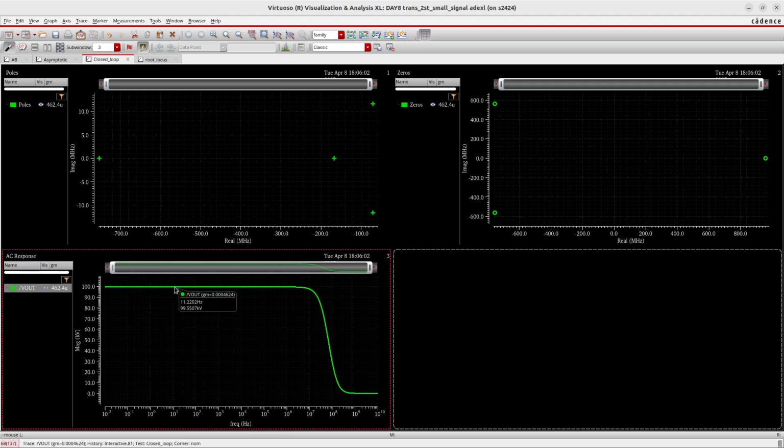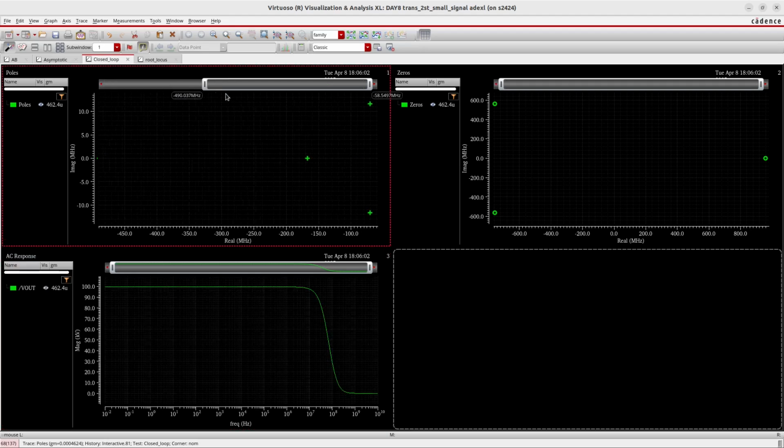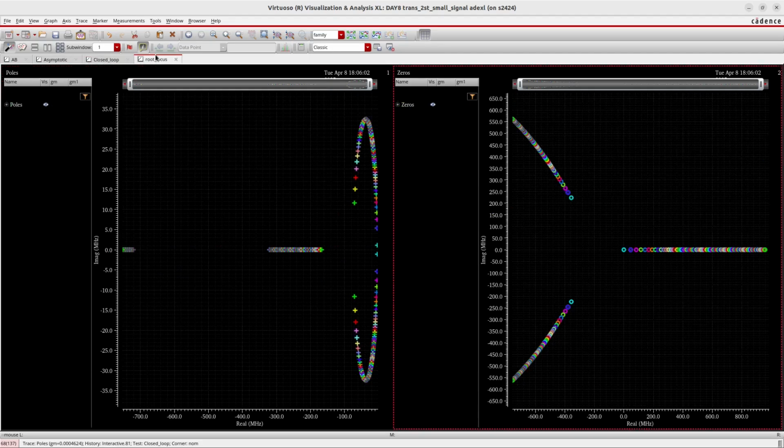Obviously we have a two-stage amplifier, and this is 99.5. The system is stabilized with this phantom zero capacitor that we have there. It has actually not been done a really good job, so it is not in Butterworth positions, but it is stable, and we are going to assume for now that it is okay.